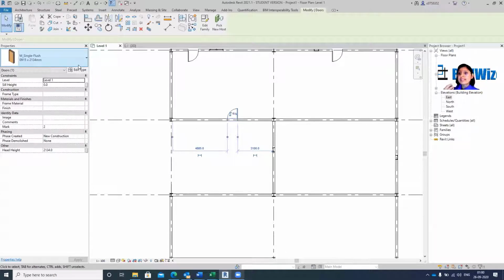Revit, Autodesk has reserved the right of creating a wall or a floor assembly. We call it a wall assembly or a floor assembly because it's not just one thing. It is an assembly of various items. So a wall is not just a wall. In here, we do vapor barriers and thermal barriers and finishes and stuff like that. So that's called a wall assembly. So a wall assembly, you cannot create from scratch.